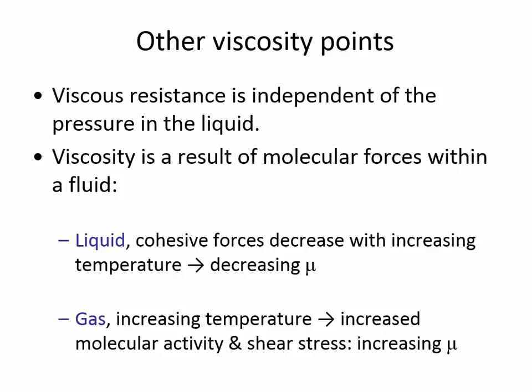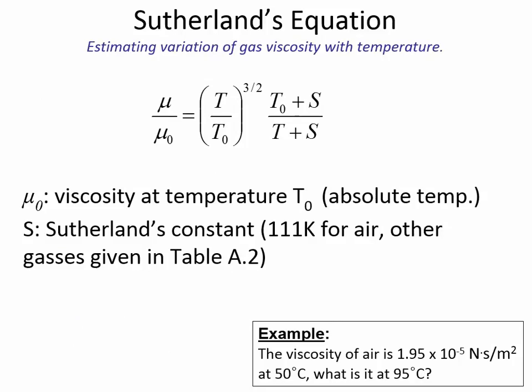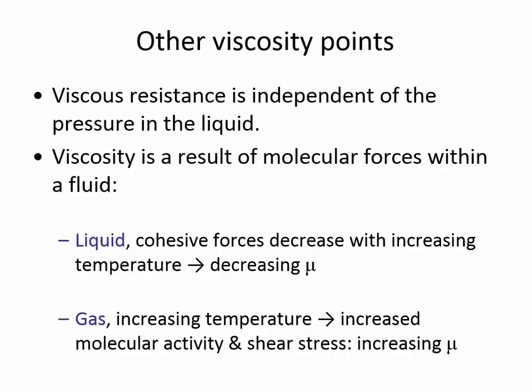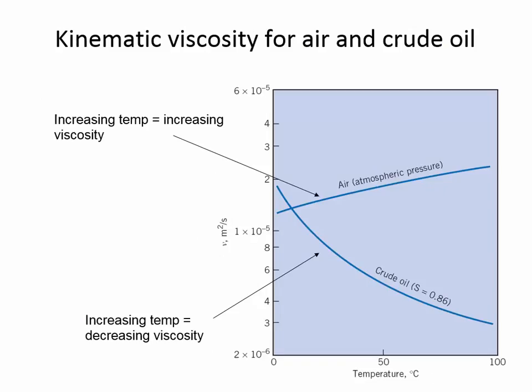But it's kind of an interesting contrast in the sense that for gases, when you increase temperature, the molecules are moving around a lot faster. And because of the collisions and the increased shear stress, that increases the viscosity of gases. And so we'll see an illustration of that in, well, let's just jump to it right now.